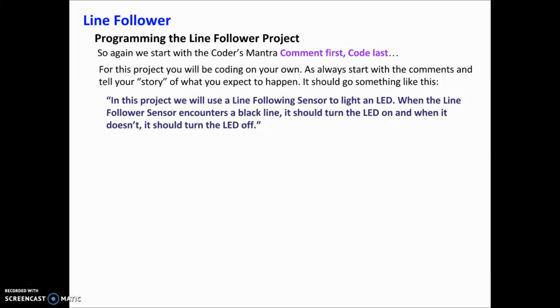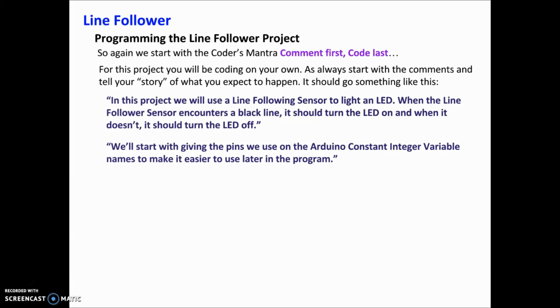All right, so in this project, we're going to use the line following sensor to light an LED. Now, when the line following sensor encounters a black line, you should turn on the LED, and when it doesn't sense a black line, you should turn the LED off. Okay. Now we'll start by giving the pins we use on the Arduino some constant integer variable names to make it easier to use later in the program, just like we always do.